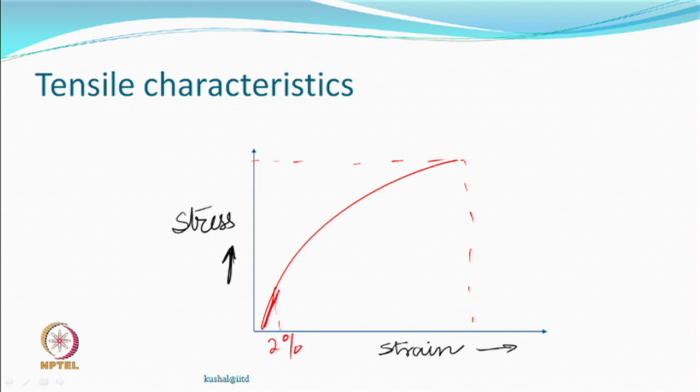Because a large number of filaments may not be contributing towards this resistance to motion at some stage. So, maybe a good number of filaments are actually transverse to the direction of force, and so they may be weaker also. So, the tensile strength may go down and sometimes extension also will go down.